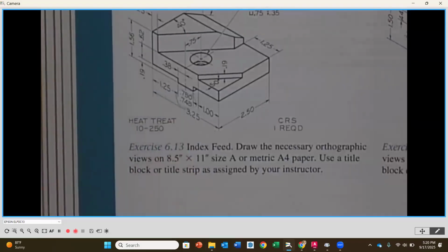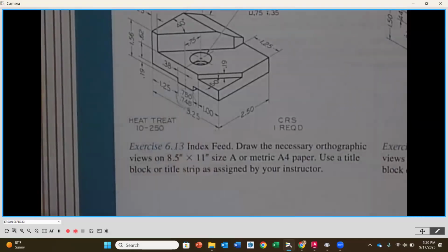So when we draw it though, we want to look for one of 2 things. Number one, is there a nominal dimension in that limit? And there is. The top limit is 0.75 and the lower limit is 0.745. You draw then to that standard number, that basic dimension, that nominal value, okay, that falls on a common inch increment. Okay, so we're going to do it at 0.75.